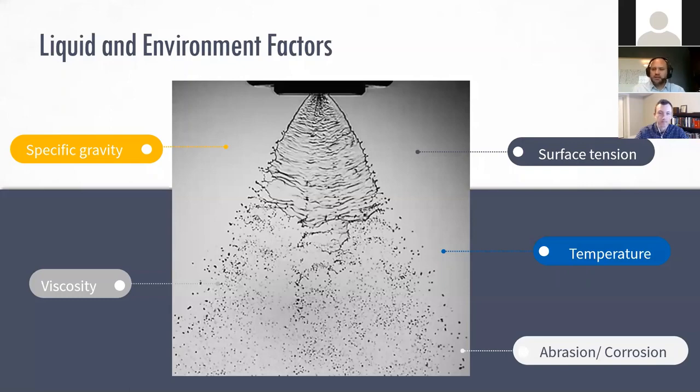And that 5 to 10 degree difference had a massive effect on the viscosity, which then impacted the amount of misting of the oil, and it created a large health and safety challenge throughout the plant. So these parameters, while simplistic in nature, can have massive impact on your process.